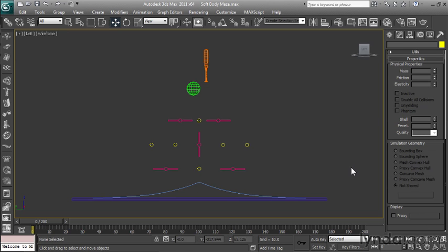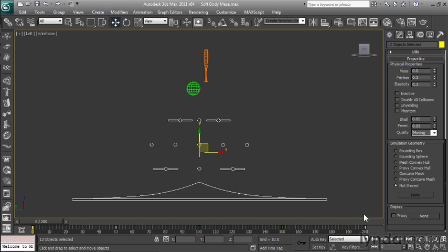With the physical properties set up, we can now start thinking about a collection for these guys. Being that they'll serve as our simulation's non-deforming rigid objects, we can throw them all into a rigid body collection. We'll select everything in our scene below the bright green ball and we'll head to the toolbar on the left. Way at the top of the toolbar, we'll find our rigid body collection. When you've located the command, go ahead and click.